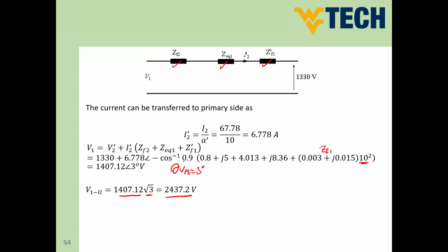Okay, this is theta V1 as V phase. Okay, now the question, can we calculate the power factor from theta v phase or theta v line? Yes, you are right. All of the time, power factor is cosine theta v phase minus theta I phase.